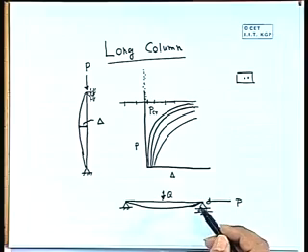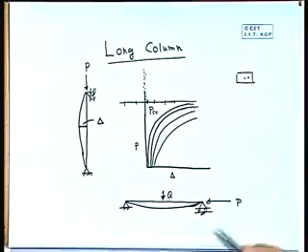Say P is not there, due to Q we will get some deflection. Now if we add P, what will be happening? Because P into that distance will give some additional moment. Due to the additional moment, there will be a further change in the deflection, right. Now P into that additional change will generate a second level of moment, so that will cause further deformation of the structure.